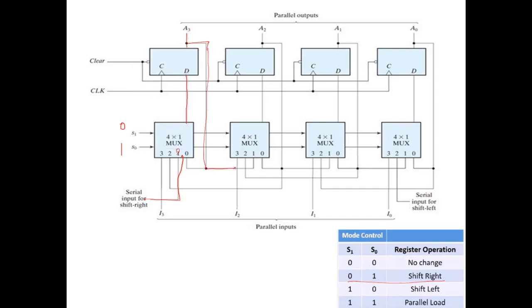Then when the selecting inputs are 01, it selects this data line, and the data input is connected to the output. It takes this input from the 4-to-1 multiplexer, the D1 input, and gives that output, which is connected to the D1 input line of the next multiplexer.